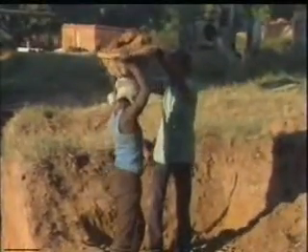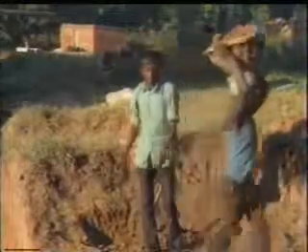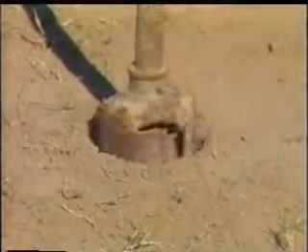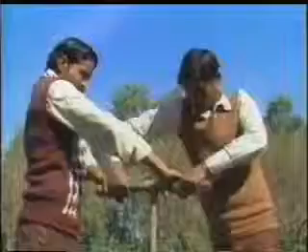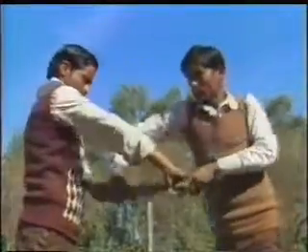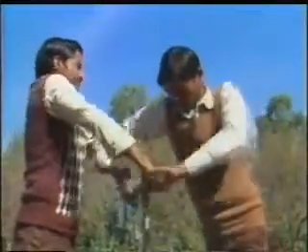To collect samples from desired depth, access is made to desired level by excavation or by means of bore holes. To make an excavation, the soil is removed by digging with pickaxe or spade. Soil is then collected in a canvas cloth or a basket.